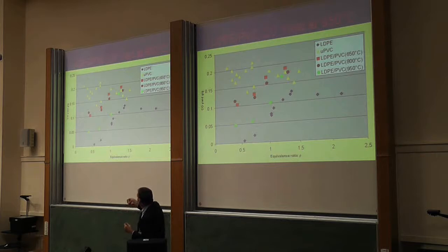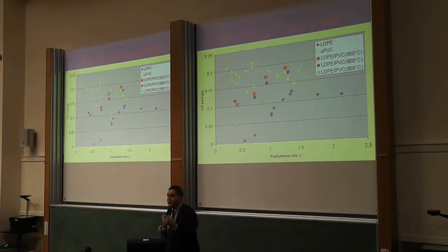We're losing that beneficial effect. So when the temperature gets up to something like 950, maybe in a developed fire, you actually lose any of this inhibition that you get from the presence of the halogens. You also have lower CO yields, certainly when you've got well-ventilated flames.